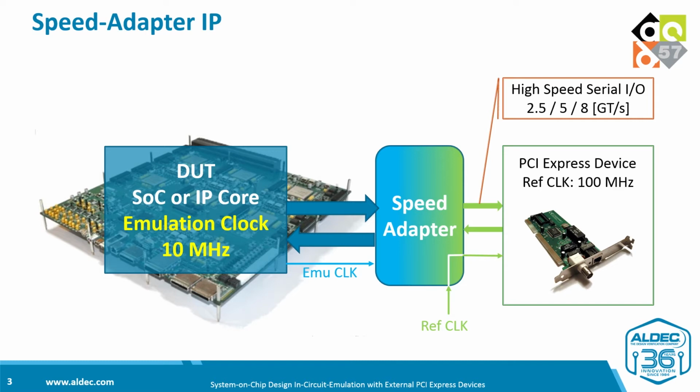For this reason, we need to use a speed adapter module that on one side connects with the emulated design and synchronizes to the emulation clock, but on the other side it connects to the reference clock and to the high-speed serial I/O lines of the PCIe device.